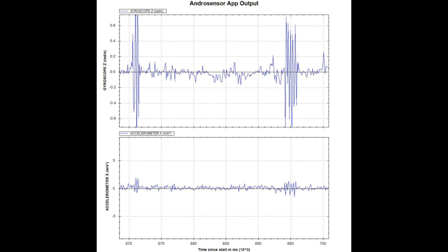You can see the gyroscope data going up a little bit, then goes down a little bit for making the right turn. You can see the accelerometer really quiet. Nothing on the gyroscope or the velocity of the steering wheel more than 0.2 radians per second. So all quiet. This is how I think a normal human would be, and I think this is quite a bit different than what we've been seeing with the robotic Autosteer going on, which we've been experiencing dramatic changes in radians per second of the steering wheel, and also acceleration happening within the vehicle.